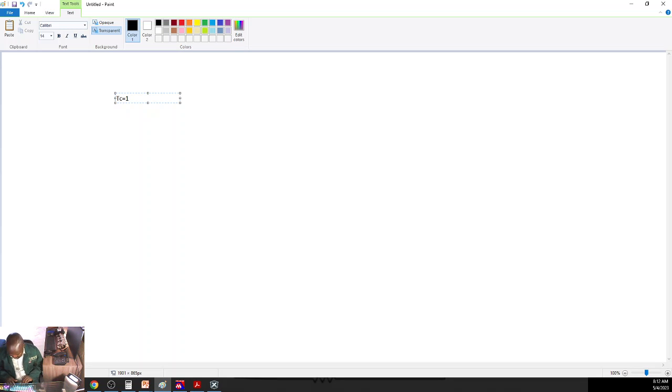1 divided by the frequency at which the timer is running. The timer is running at the same rate at which the instructions are being executed. And the instructions are executed at a quarter of the oscillator frequency. So a quarter of the oscillator frequency will be your F oscillator divided by 4, right? And then that will mean that your timer 0 is running at 1 divided by your F oscillator, which is 4 megahertz,